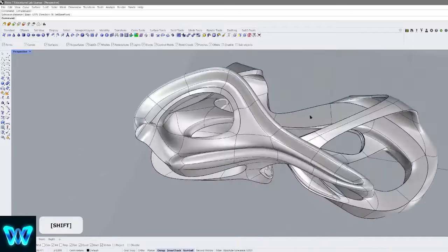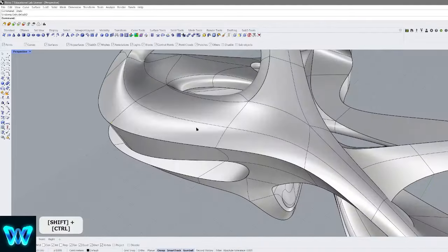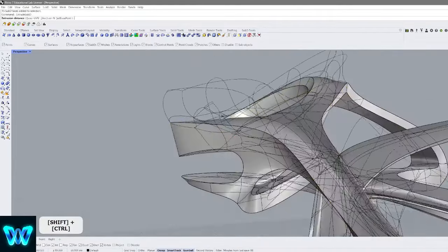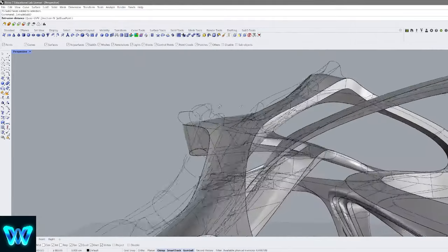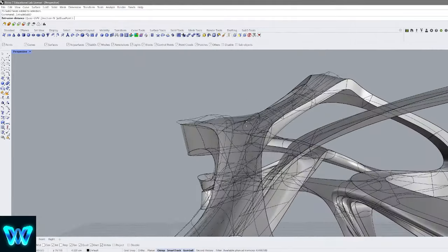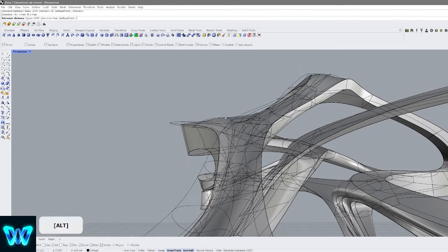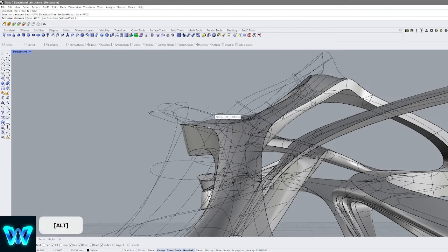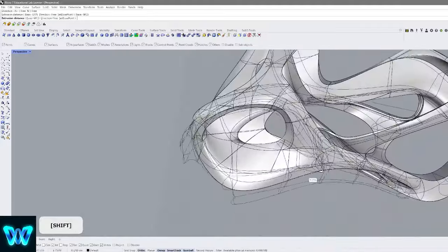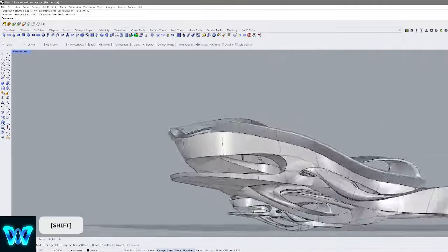You can create interesting forms. At the same time, you can change the direction where they're being extruded. In this case, they're all being extruded tangent to their specific face, but you can change the direction to be free. It can be free to whatever position you want, and you can change the basis to a specific axis. So I can do it to the z-axis, but that never really works.